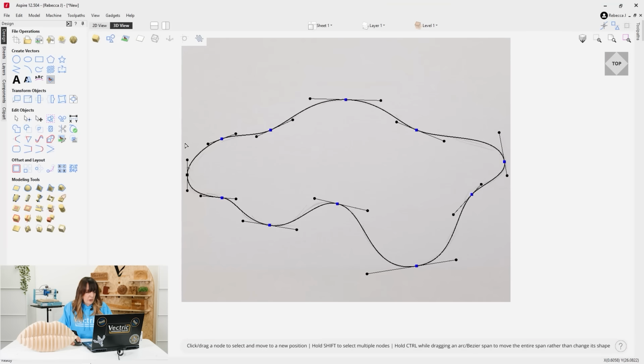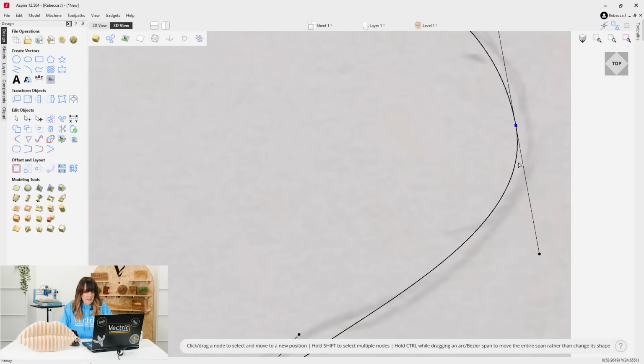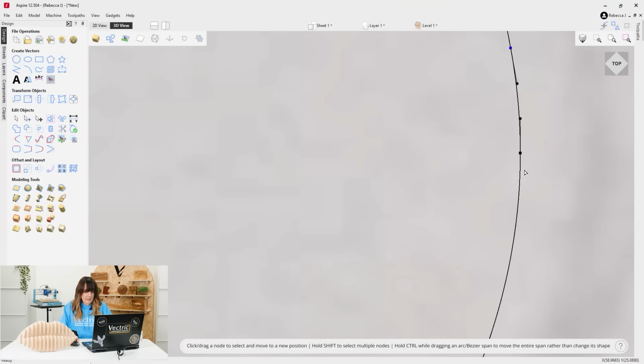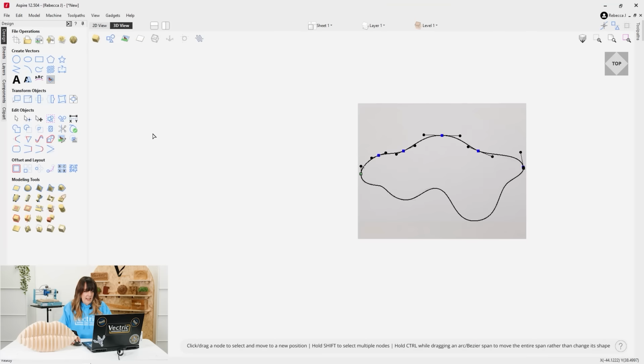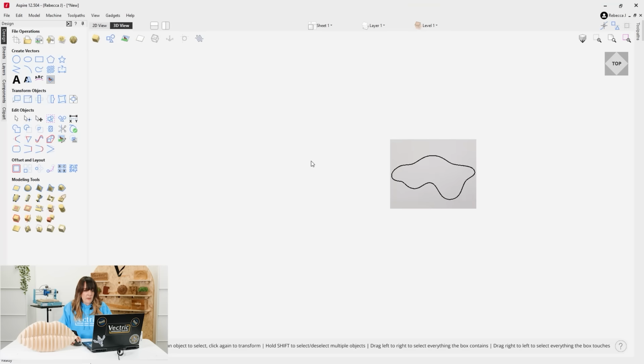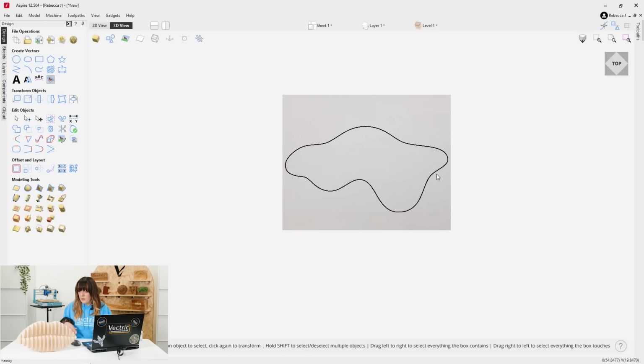and I'm actually just going to cut the vector at 2 points, so one on the left side and then one on the right side. I'm trying to again hit that apex, so we'll just put a C there to cut that. So now I've got 2 separate parts. Right click to come out there, and now we're ready to draw in our profiles that we're going to sweep to create our blob model.